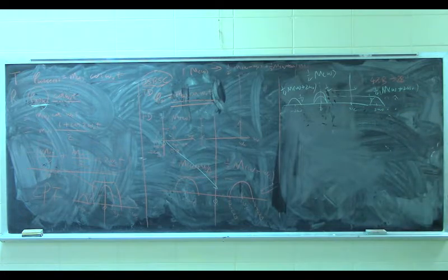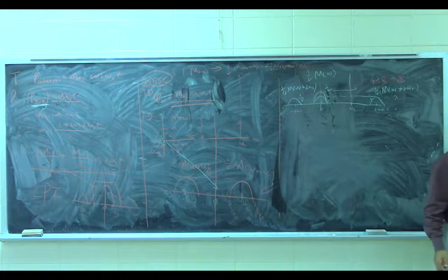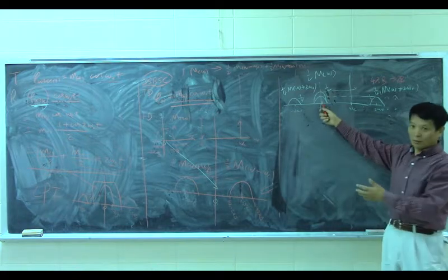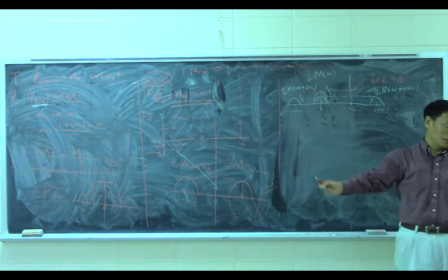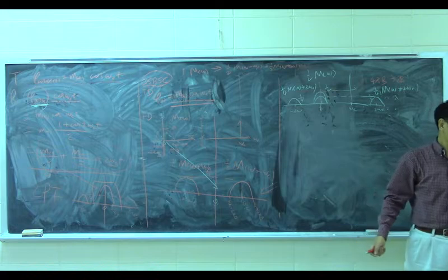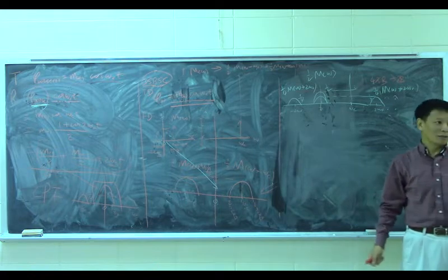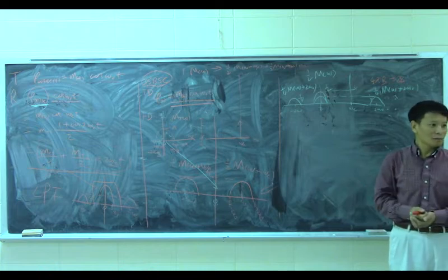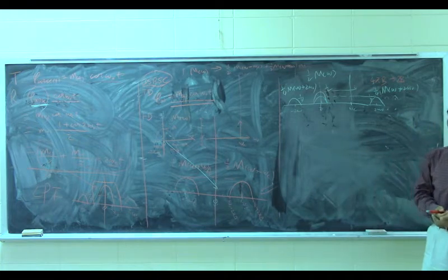What's the point of copying it on both sides if you can just get the original signal from one side? Is it like a result of something? Okay, that's a very good question. His question is, if we shift only one, we get this one. So we already have this one, although it's just a quarter, right? That is called single sideband. We are going to discuss this later, but right now you're going to use double sideband. This is the next topic.